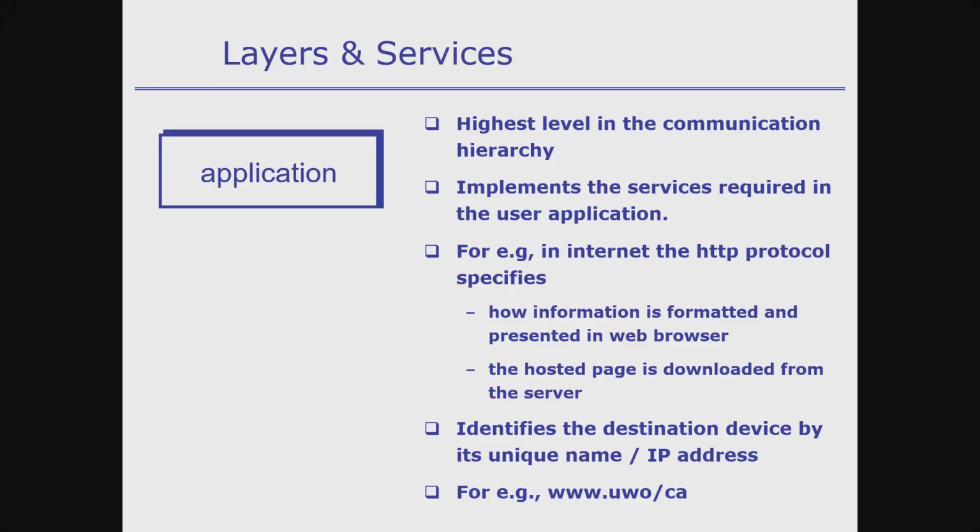When you are talking about not needing all layers, the standard that we are going to talk about, IEC 61850, is going to define which services need how many layers. And if all the devices are following that particular standard, then obviously they will all have the same number of layers, so communication is not a problem. Obviously, if they are not following the same standard, then they can't talk to each other.